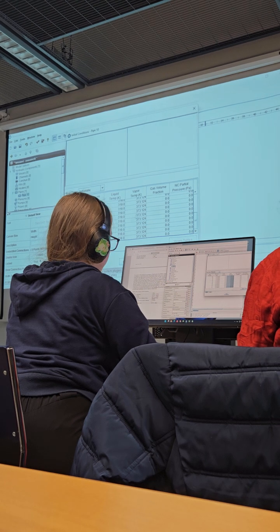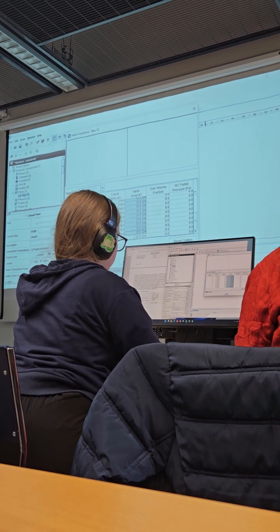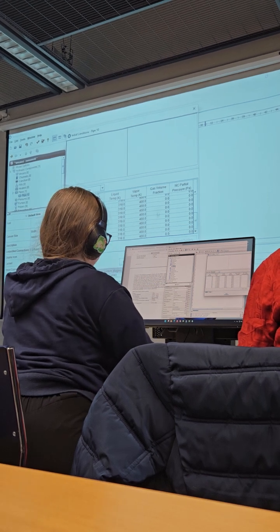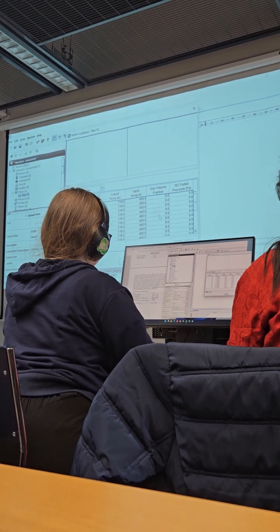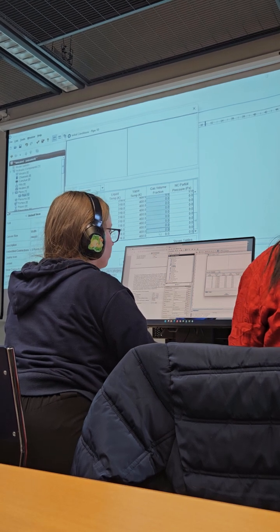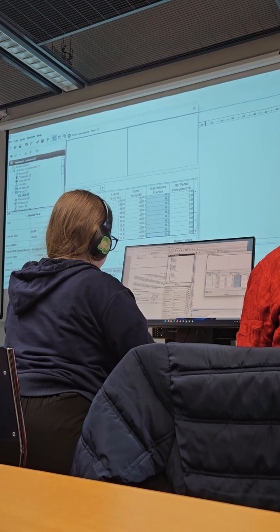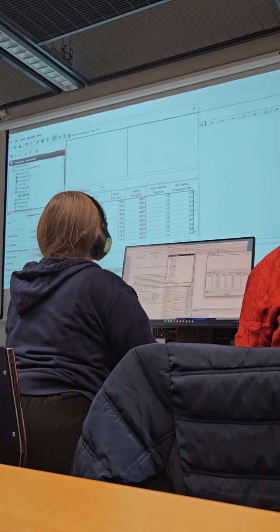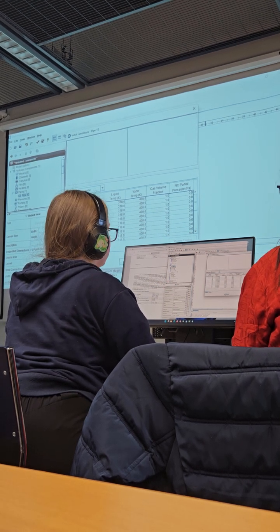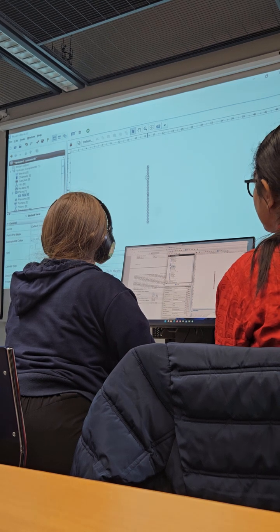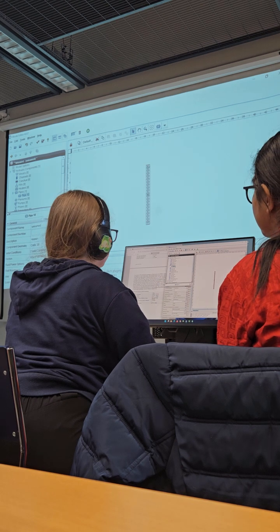318 and 400 for the steam. And first of all, since we don't have any water inside the glass tube, we just change the gas volume fraction to 1. We have steam only. So then the initial parameters for the pipe are already modified. We just need to make a few changes here in the modeling.